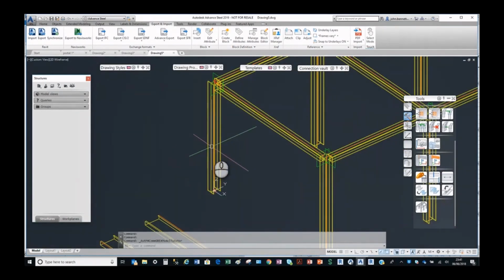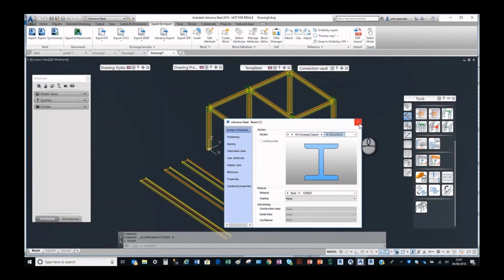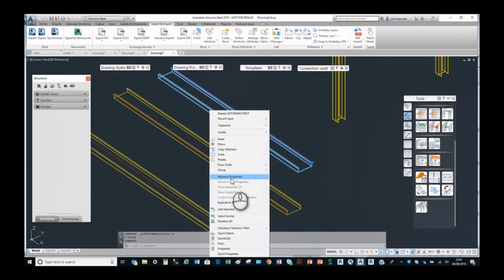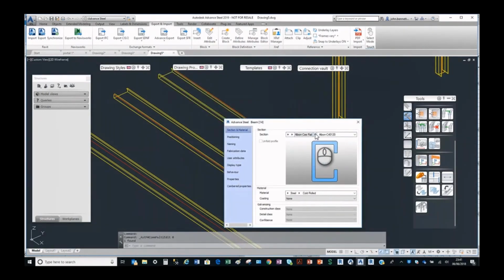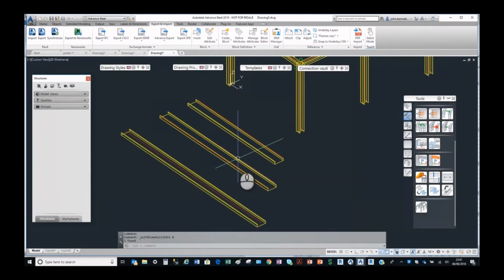Obviously the section's right rotation, etc., because of the dynamic settings that I set. So we can see that this is just a basic one, and then I'm going to look at the cold rolled section now. If you look under the material, first it's pulled the beam in. The beam is dynamic because we set it that way. But the steel material says steel cold rolled, so that is the Advanced Steel material, so it mapped straight away. I didn't have to go in and do any funny mapping. And that is the same for all the sections here as well.